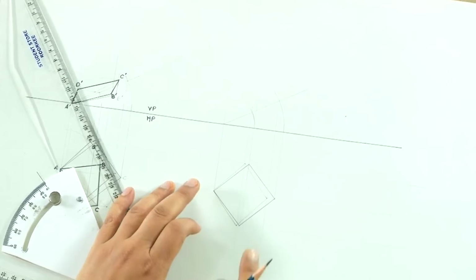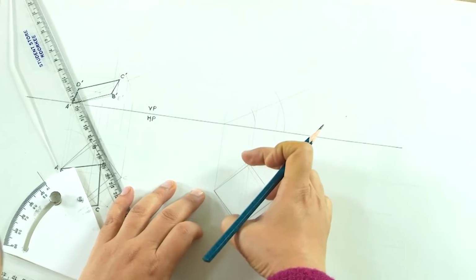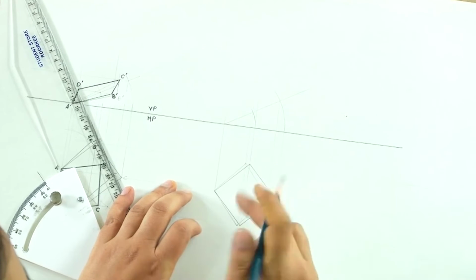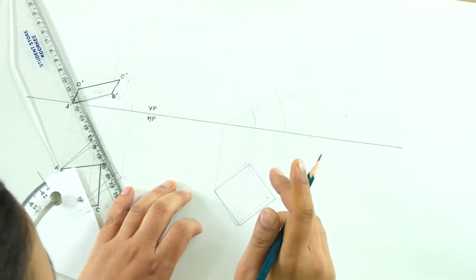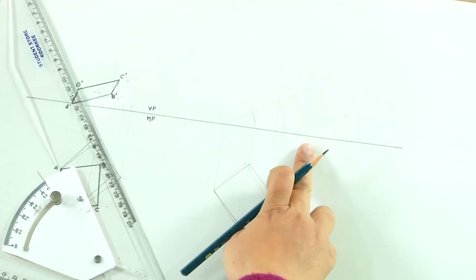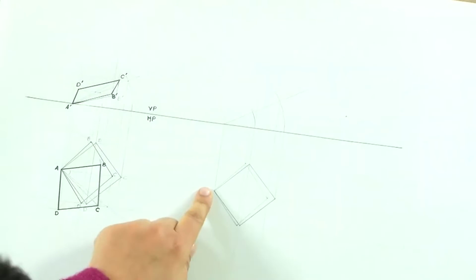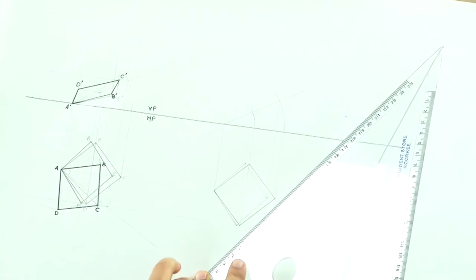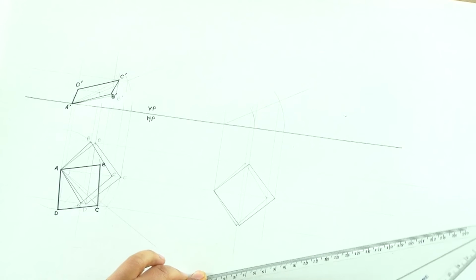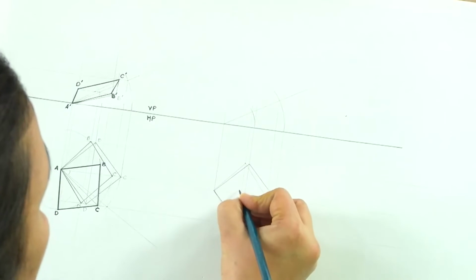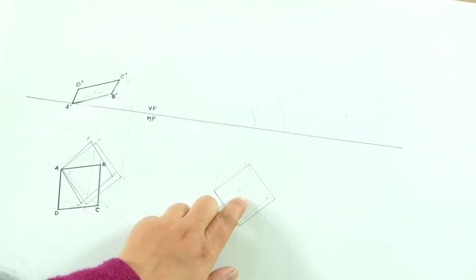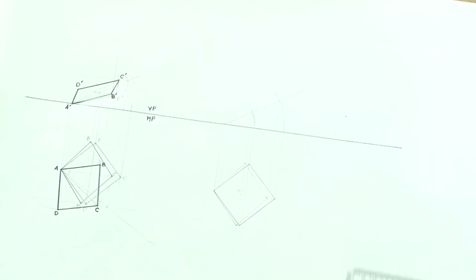Now, we have to incline this BD about A by 60 degree, so that it makes an angle of 60 degree with the VP. So, through A, the square will still be rotated in such a manner that this BD now makes an angle of 60 degree. Suppose this is the new point O, which was the center of the square, the distance from A to O remains the same and the point is rotated. So, what we will have?